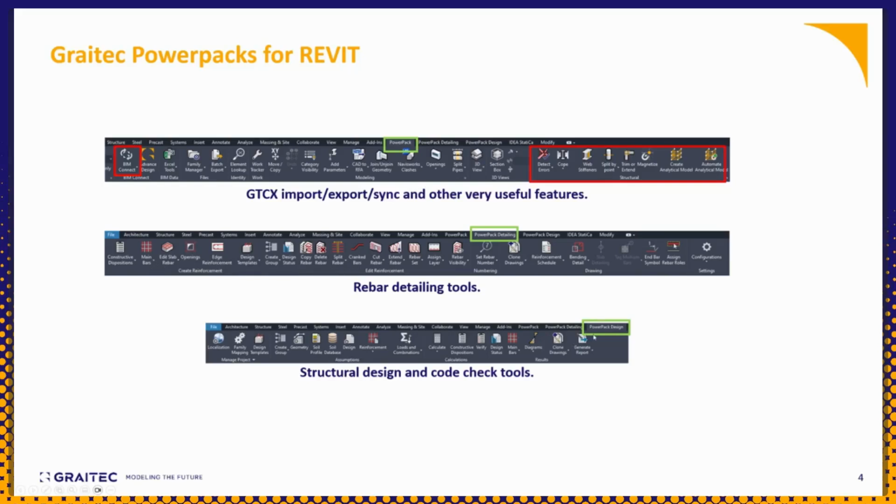The other tool, PowerPack Design, is based on the internal loads. It's going to do the design and rebar placement based on the codes that you are using. We have the localization here, so different country codes that you can select, and based on the forces imported from Advanced Design, in this tool, PowerPack Design, we can perform our rebar detailing based on internal forces, FEM forces coming from Advanced Design.